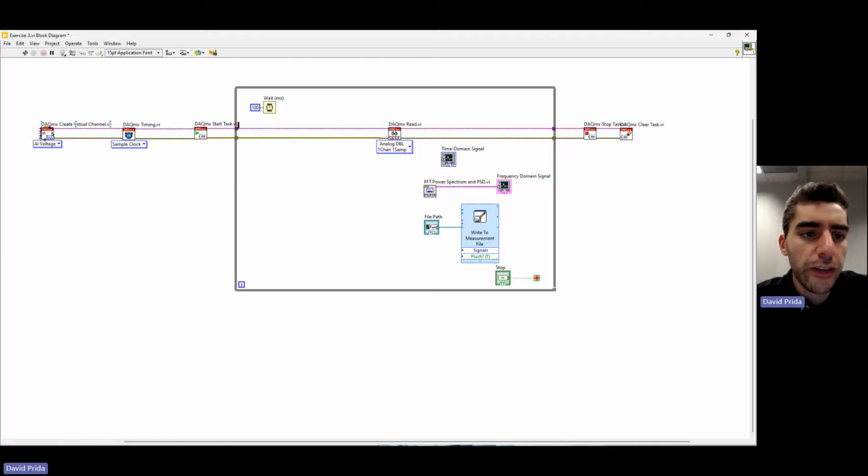So now we can see the create virtual channel, the timing, the start task, DAQmx read, and more. Sorry, just trying to make sure everything is organized. So everything is wired. We have all the labels set properly. Let's now go ahead and set up our create virtual channel.